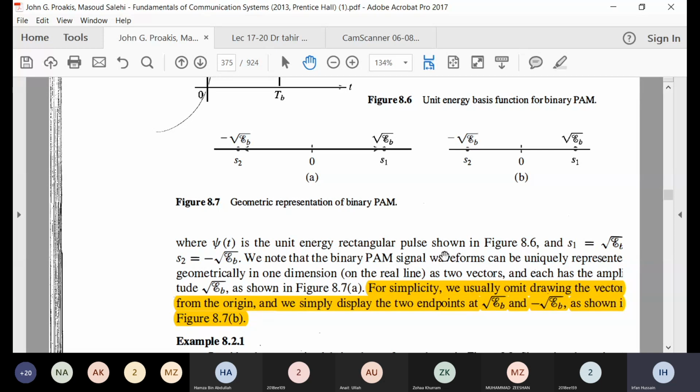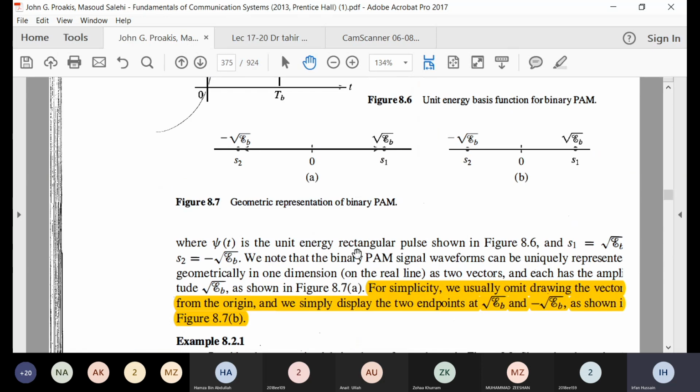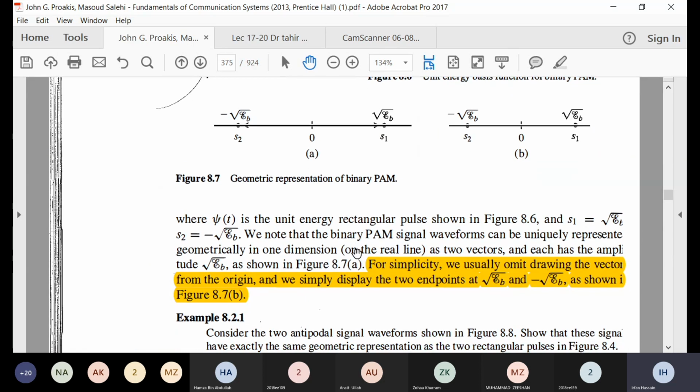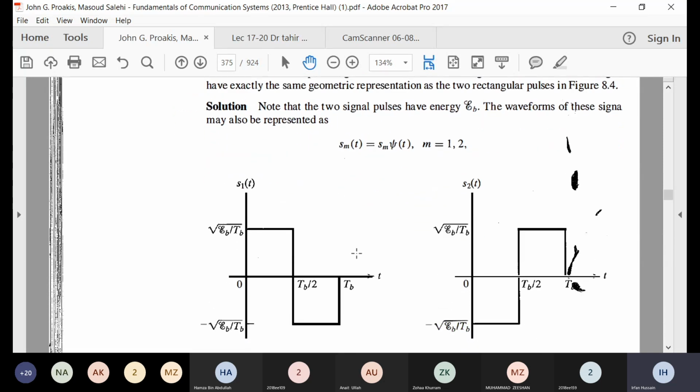All right. So you could see I have also clarified in the notes that you can represent them. Another example the book has done, and for this example again you have these two signals. Again you can notice that this signal is antipodal of this signal, because this signal is exact negative of this signal. You just multiply by -1 and you will get this signal. So again you can very well see that these are both antipodal signals. You will have just one orthonormal basis that can easily be found by dividing this signal by its energy.